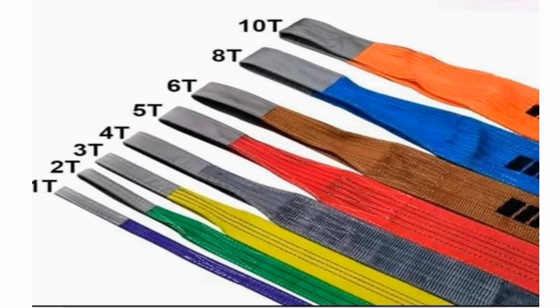If the load is small in size and shape, we can use a 1 ton 1 meter sling, for example. If the size is big, maybe this is only a 500 kilogram pipe, but the pipe length is big, meaning the length is more than 2 meter, then we cannot use the 1 ton 1 meter. Then we have to identify the correct size of the web sling. That depends upon the size and weight.